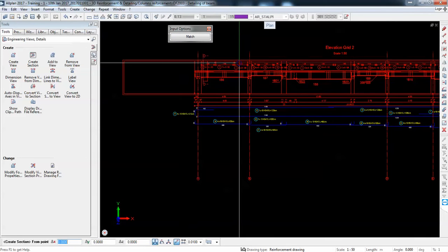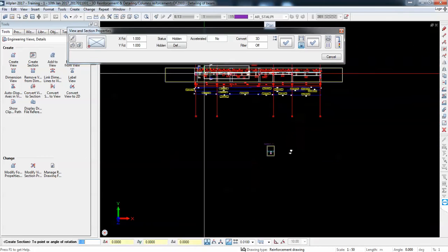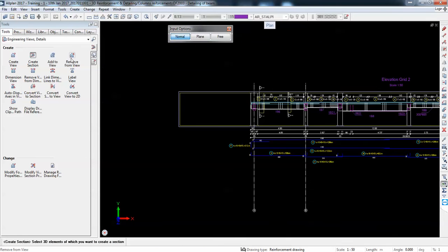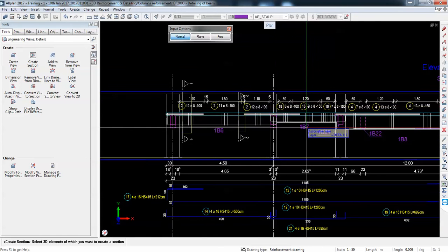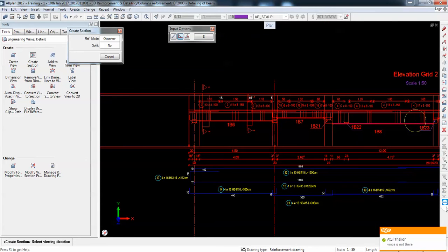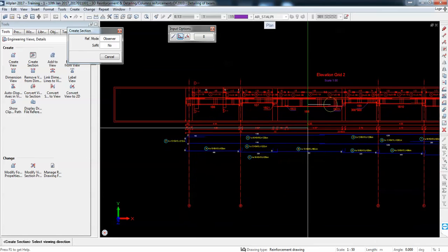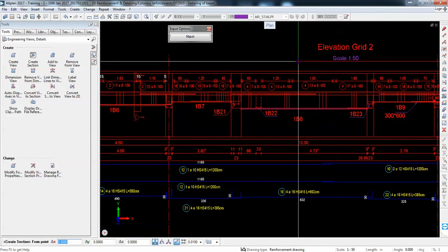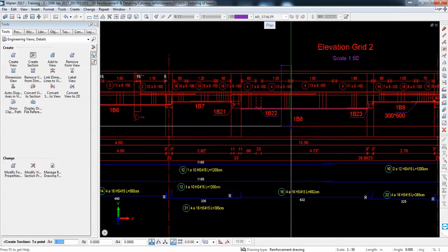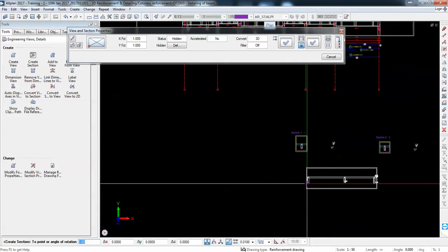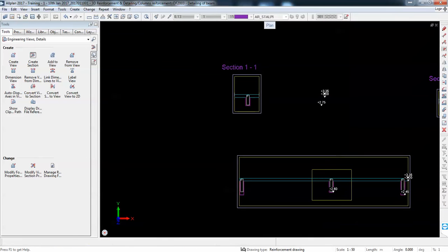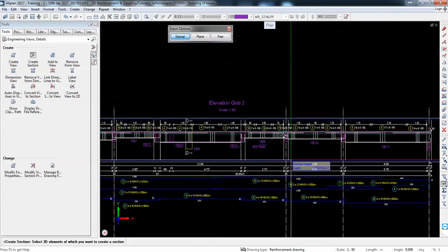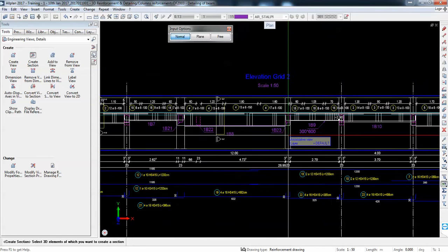I'm going next with others. So based on these bars, I know how many sections are relevant for me, and I don't need to place them in a very orderly fashion or aligned already, because they are somehow irrelevant in terms of detailing until we change the scale. What I was saying was that we only have to pay attention here not to do the section where we have an overlap, because we'll see 2 bars, and where we should place the endings, because according to the endings we get this positioning of the triangles. From this point of view, it's irrelevant where we place them, as the detailing should be 1 to 15. So it's not important how they look on 1 to 50 at this stage. On 1 to 50, it's important only where we place the triangles to get a nice representation.